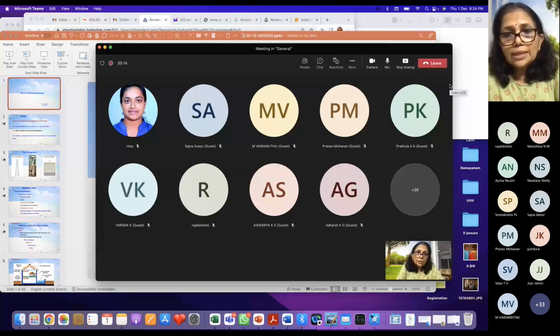So what kind of stresses are developed? When it is bending, you know how it is bending? How it is deflecting? It is deflecting downwards. When it is a simply supported beam, it will deflect downward. So when it is deflecting downwards, the top surface is subjected to compression and the bottom surface is subjected to tension. You've studied this. So because of those stresses, a stress resultant will come. That stress resultant is the bending moment.